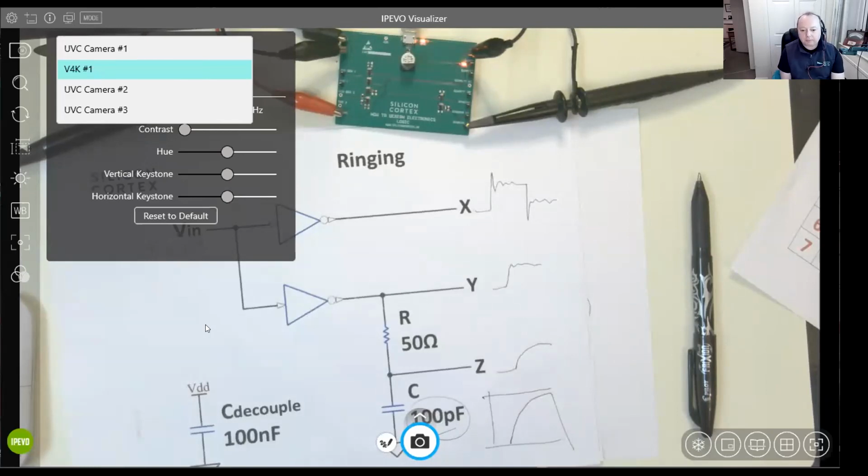However, we have had issues with this on the ARM Cortex M range. We actually did have a differential I2C to go off board, and we actually managed to make the ARM core hang under EMC conditions. And it took some clever filtering and some very clever PCB design.